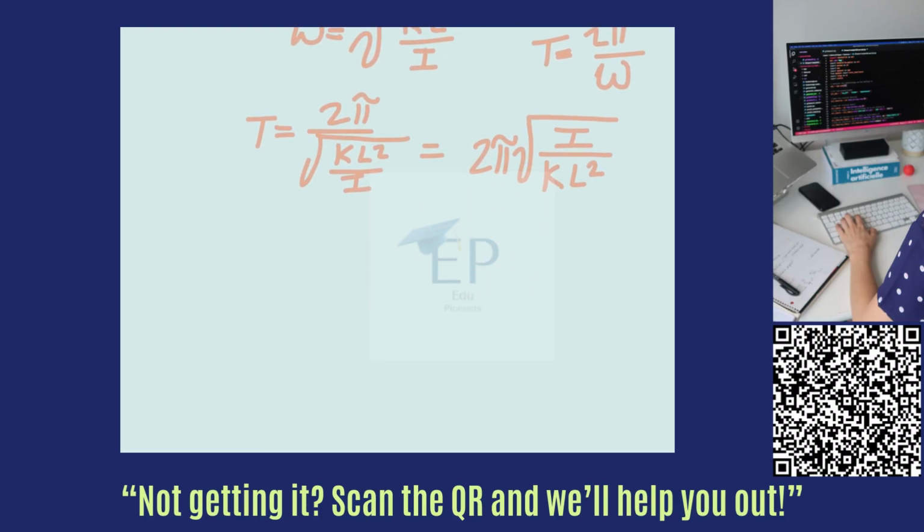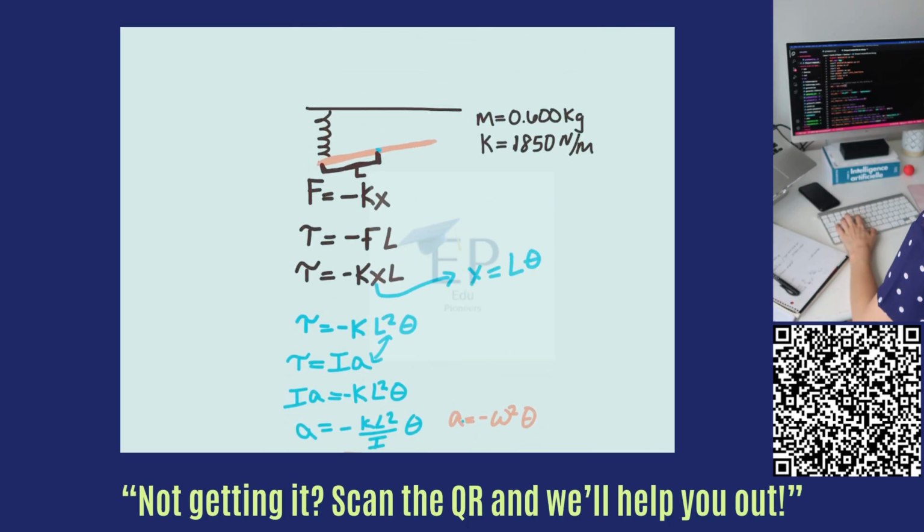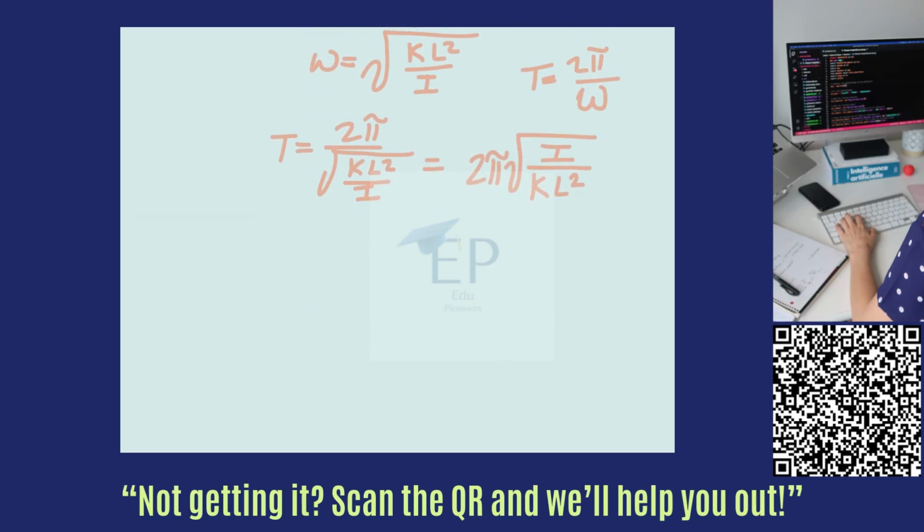All right, next we need to figure out inertia and get it into terms that we are going to be able to work with. And since the length between the center and the end is L, then the length of the full rod is 2L. So we can use that to find our inertia using the equation for a rod with a length of 2L rotating about its center.